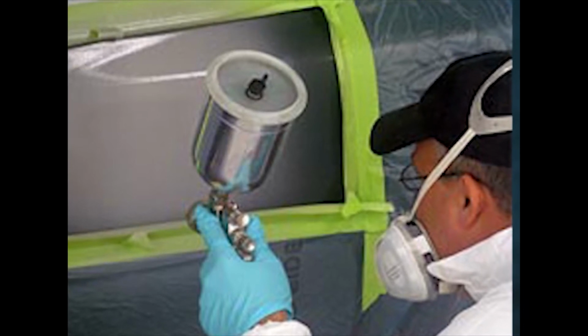Now comes the primer surfacer. These are epoxy modified urethanes and polyurethanes, and the main function of the primer surfacer is to smoothen out the surface while hiding imperfections, as the base coat is the next layer to be applied. This layer is highly pigmented. Color pigments are used to minimize the color contrast between the primer and the top coat.